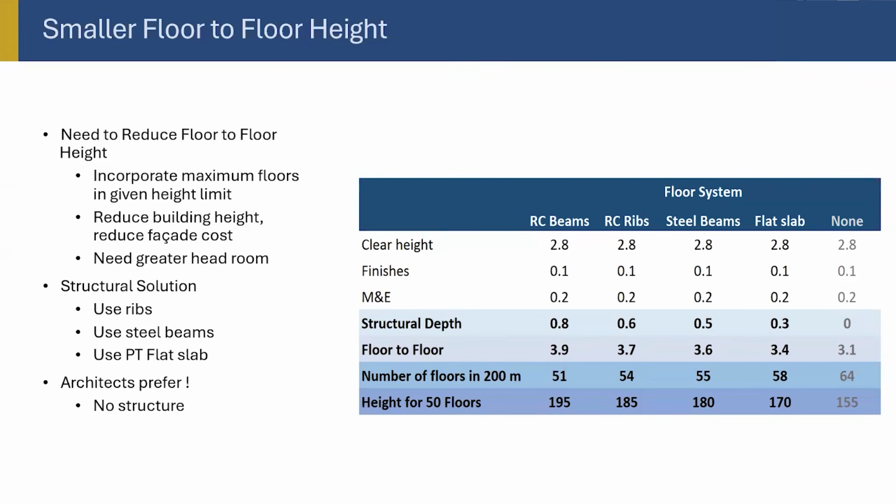And if you go back to the building codes, you will find that it's not allowed. It's not allowed to make a post-tension flat slab in a seismic zone beyond 10 floors. Traditional codes are made that way because they are not for tall buildings. Those codes are for typical buildings.